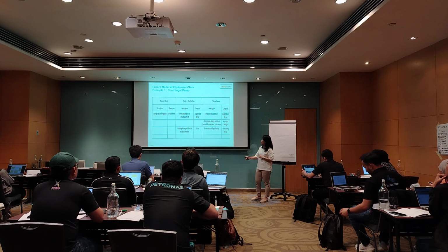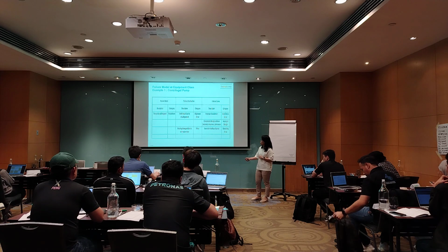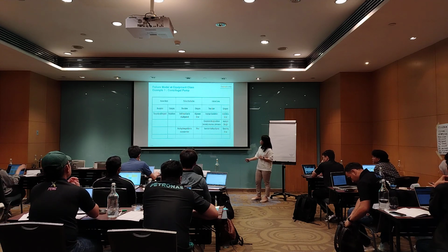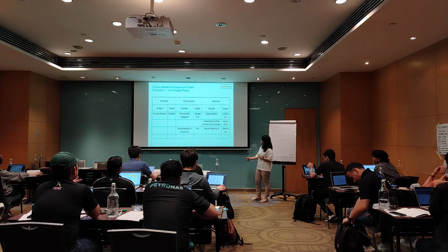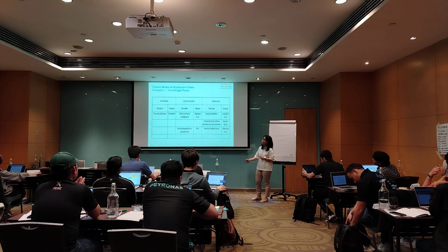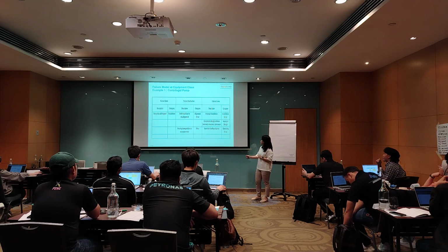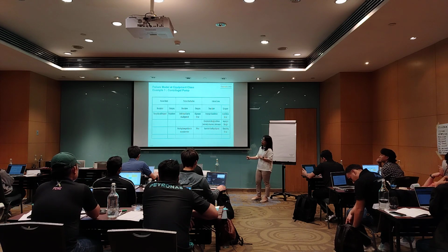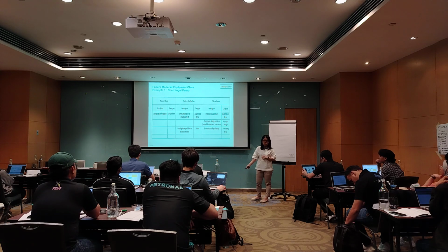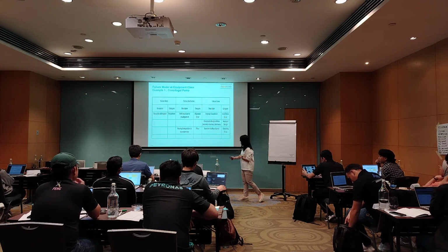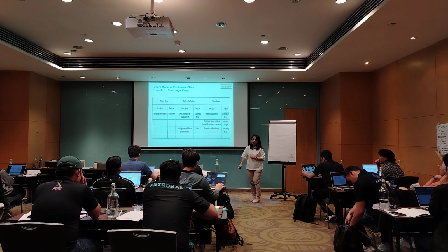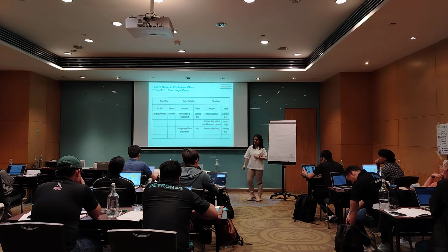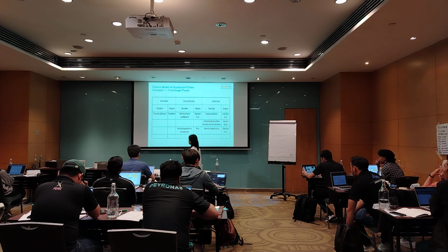The pump seizing can be due to bearing damage due to excessive wear. And then the cause will be excessive loading of the pump. So this is the kind of failure causes you saw just now also, by category. Any question? No question.